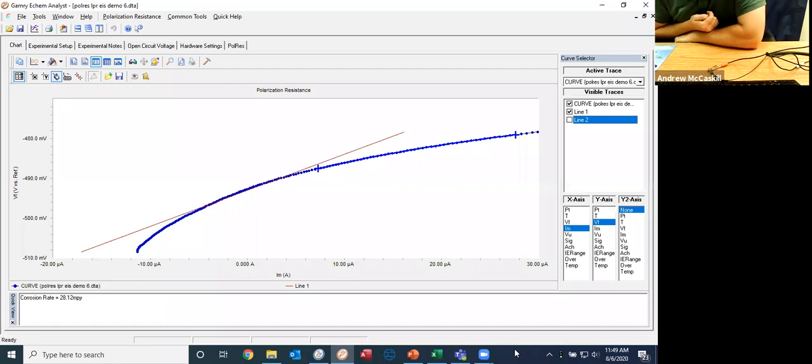But one thing I would point out: when you say LPR is destructive relative to EIS, if you ran LPR constantly on the same sample over and over again, then yes, you're eventually going to corrode the system. But if we're only applying 15 millivolts on either side of OCP for just a minute or two, then, as I said before, it's an active experiment. You're perturbing the system, but I wouldn't say that it is fully destructive. It's kind of in a gray area.